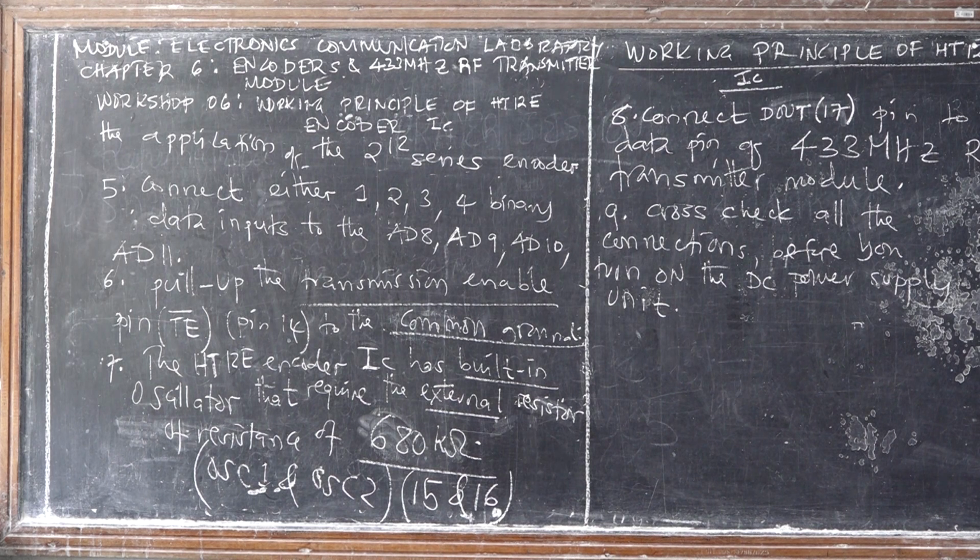In most cases, in your cross-checking, you have to use the continuity tester or continuity check. But you can also perform a visual inspection. Why? Because in case there is a short circuit, when you turn on the DC power supply, you are going to damage some of the electronic components. So it's better to cross-check several times, not only one time.